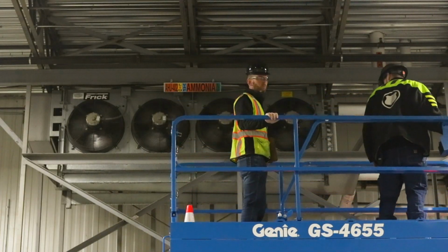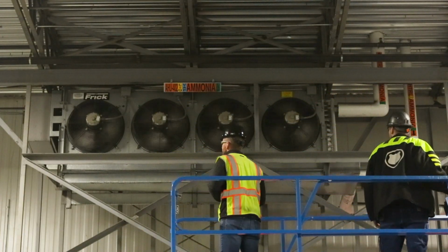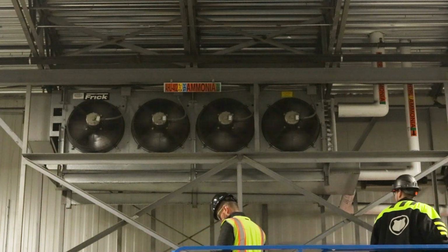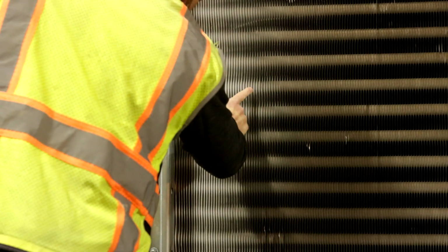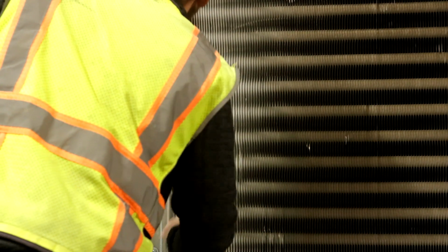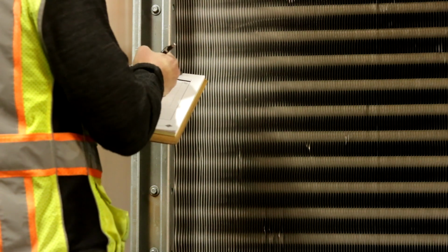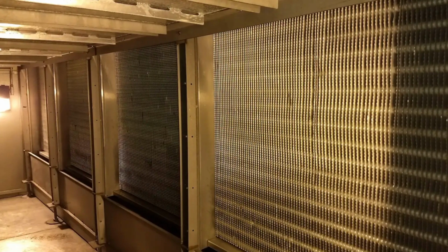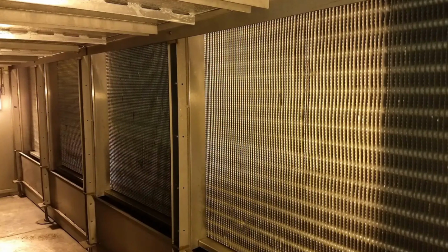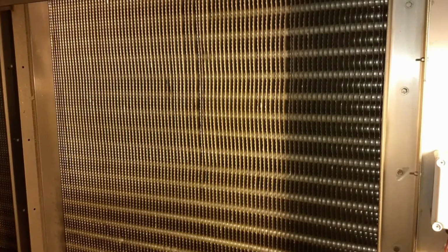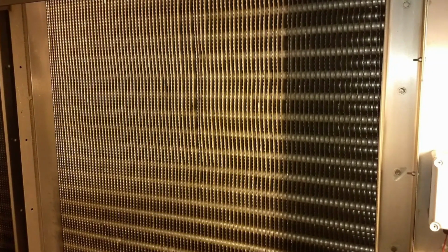Finned coils and forced air movement are almost exclusively used in air cooling evaporators today. The spacing of fins will vary based on the application of the evaporator. Evaporators used in high temperature applications, such as a loading dock, may have 8 fins per inch, whereas evaporators that operate below 32 degrees Fahrenheit will require much greater spacing to prevent ice from bridging the gap between fins and blocking airflow. Low temperature evaporators will have fin spacing closer to 3 fins per inch.